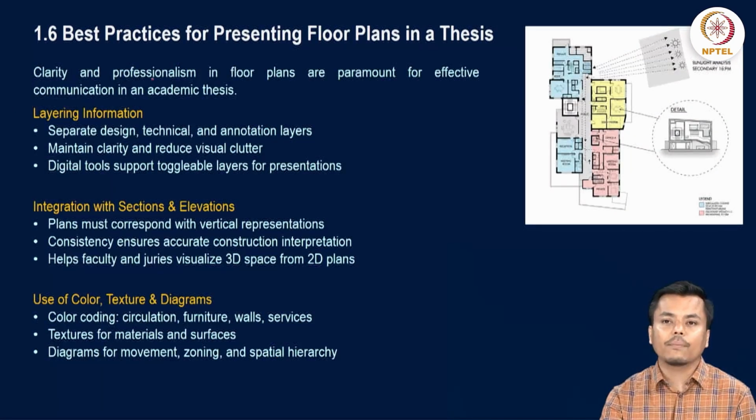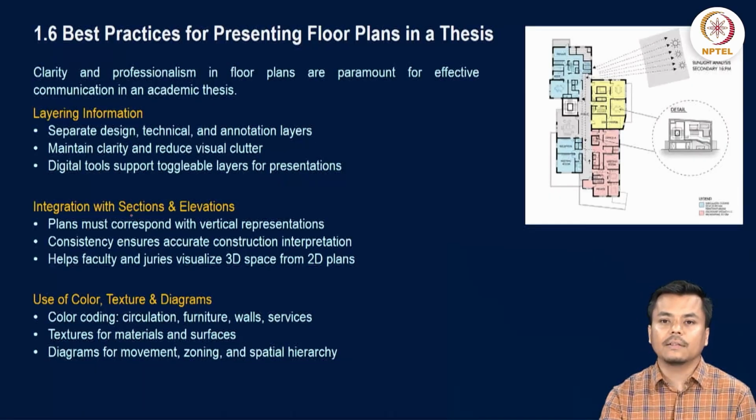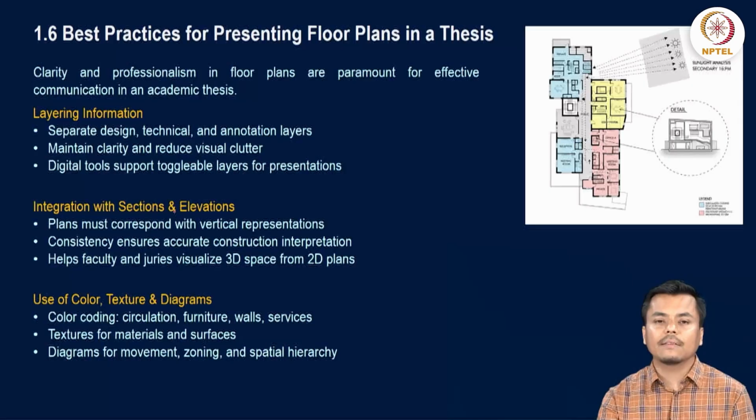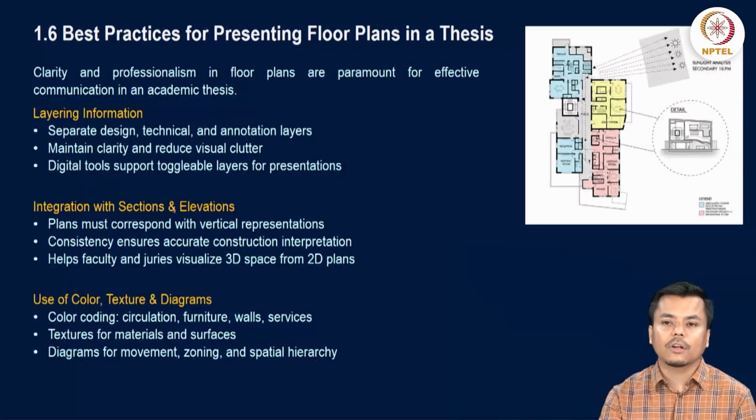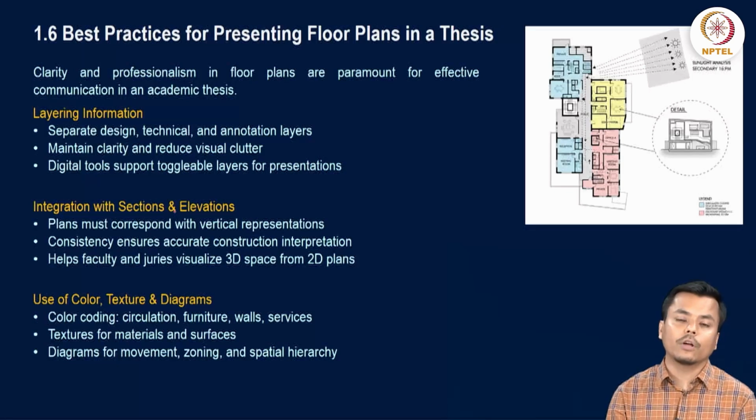So with clarity and professionalism, you also have to showcase the details about layering information, that is, separate design, technical and annotation layers. Maintain clarity and reduce visual clutter within the drawing. Digital tools support toggleable layers for presentations, and integration with section and elevation. Plans should be prepared in such a way that they correspond with the vertical representation that you have prepared, or either way, whatever elevation you have prepared should correspond to the plan that you have prepared.